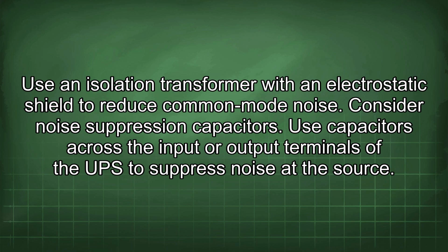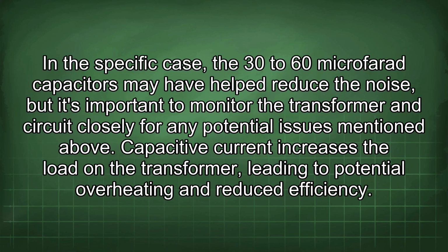Consider noise suppression capacitors. Use capacitors across the input or output terminals of the UPS to suppress noise at the source. In the specific case, the 30 to 60 microfarad capacitors may have helped reduce the noise, but it's important to monitor the transformer and circuit closely for any potential issues mentioned above.